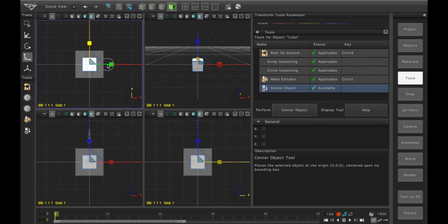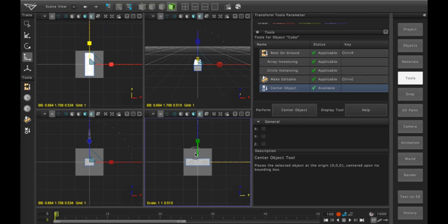Now I'll simply take and select the Scale tool, and I can take and non-uniform scale my cube by clicking on the individual axes of the scale gizmo, and I can get the correct proportions for my car. The last move will be to scale it down on the z-axis. This gives me a rough starting shape for the car.